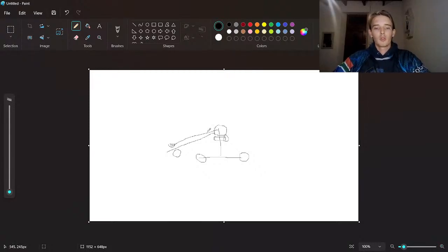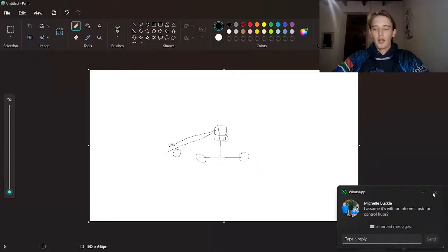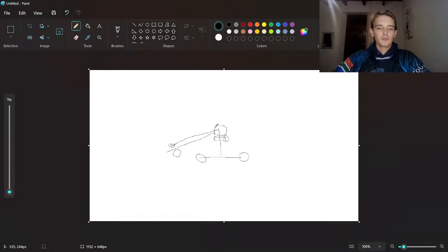So then what you would normally want to do is have a way for the driver to say, okay, I want the arm to be at position 0 now, or I want the arm to be at this position over here, which we can say is like 120 or whatever. Remember, this number is in ticks, so it's not a particularly useful number. It's different for every motor, but that just means you have to tune it for a motor. I'm going to show you how to do that. But that's just the idea.